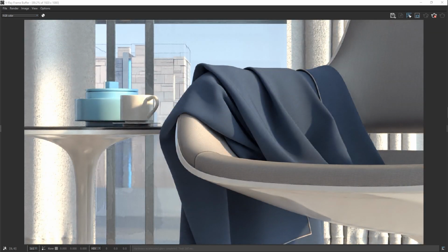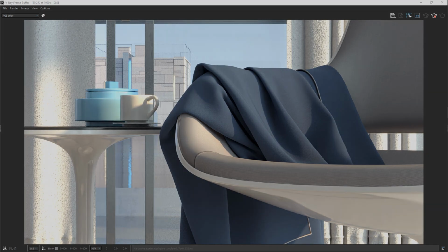Alright, now that's looking much better. We're getting a nice sheen effect, which feels natural since we copied the fabric's diffuse color as a reference for the sheen color. Now our fabric appears much more like cloth, with a gentle fall-off effect.